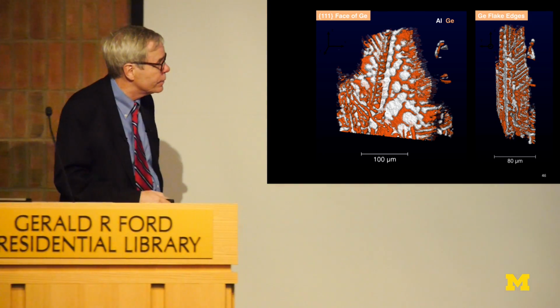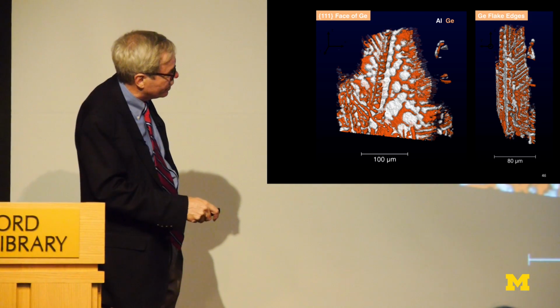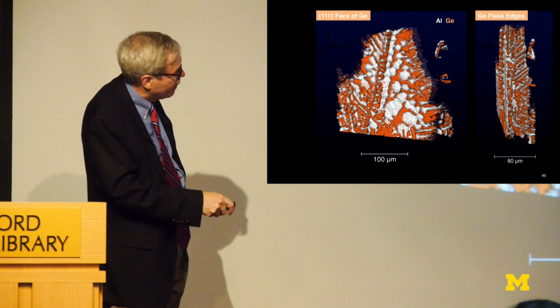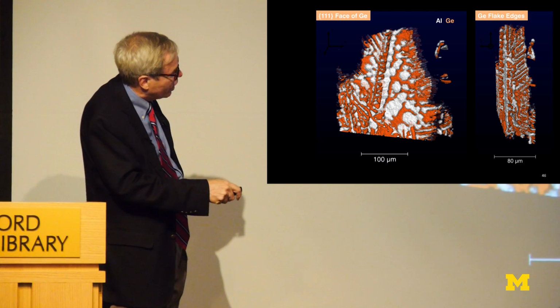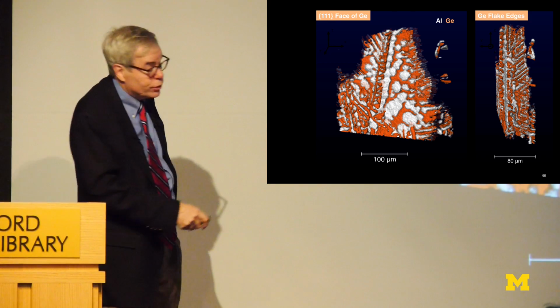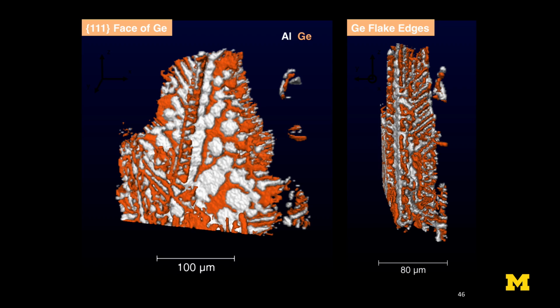They're full of twins. And the way we can see that is that this is one of the germanium plates that go, here's one germanium plate, here's another germanium plate, and then you can see on the sides here other plates that are oriented at exactly the angles you would expect if they formed by a twin formation mechanism at this point.